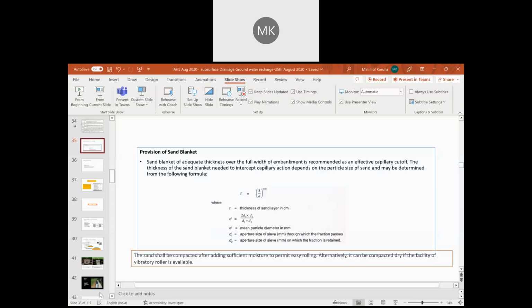Whenever you are cutting the hillside, we are going against nature. Hill cutting is the easiest way people can go, especially in the Himalayas and all, compared to extending to the valley side, because the valley side will be a deep gorge, so we tend to cut the hillside. But hillside cutting will cause more and more disasters, more and more disturbance to the natural equilibrium. So in that case, going for a drainage composite is really a big blessing.